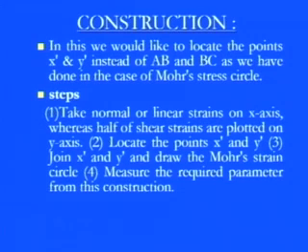Once you make the x dash y dash points at these two places, now join those x dash y dash points, and then you will have a diameter of the Mohr circle. And once you have the two extreme points of the diameter, simply draw the Mohr circle.